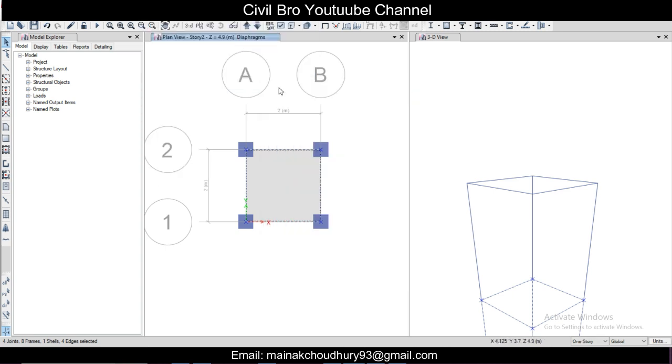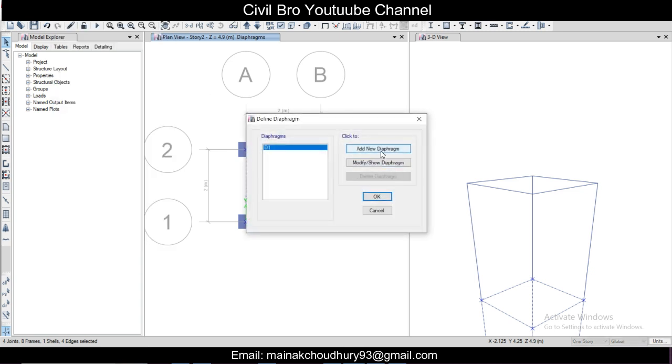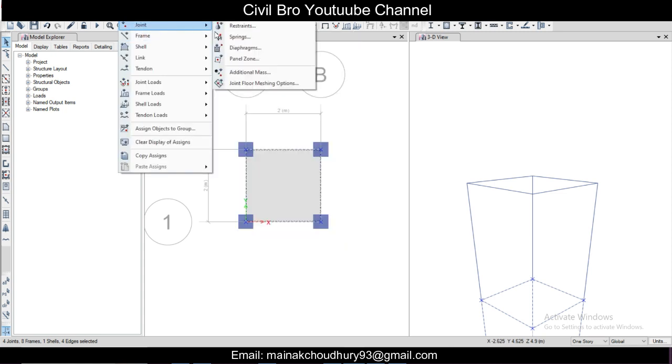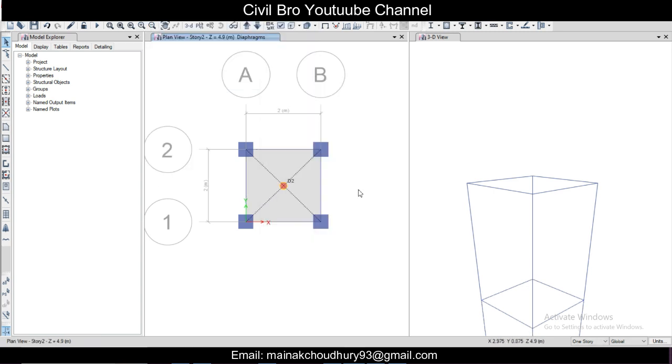Okay, select and assign joint diaphragms. D1 is not being selected, so just define diaphragms, add new diaphragm, D2, okay, and then assign joint diaphragms, D2, apply, and okay. Okay, so the diaphragm has been defined. So now we need to apply the hinge.